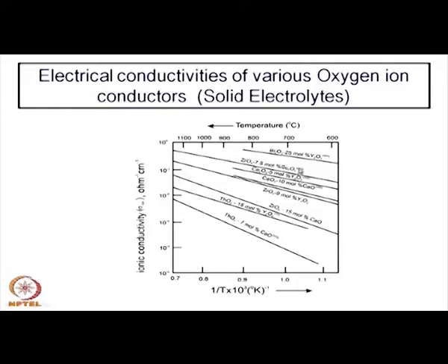Unfortunately, this is rarely used because of the very high cost of scandium, which is a rare oxide, and the non availability of this particular oxide. Cerium oxide with 5 mole percent or 10 mole percent yttrium oxide has fairly high conductivities, and can also be used as an electrolyte. Of course, it has some disadvantages, which maybe I will discuss in a minute.